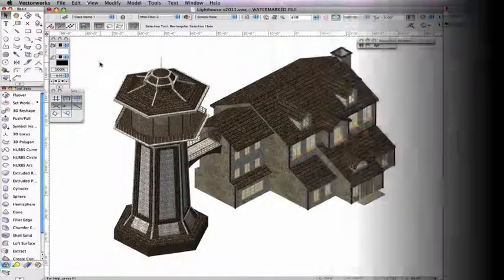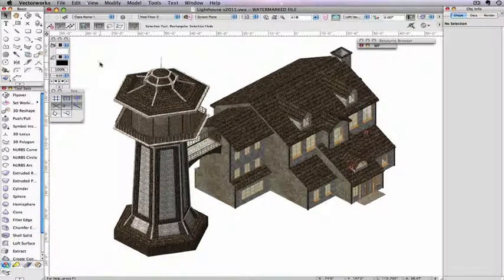There are times when designing that the listed default 3D views will not be ideal for what a user needs to check or present a drawing. In these cases, users can use the Flyover tool to create a custom view. The Flyover tool simulates movement over and around a model.